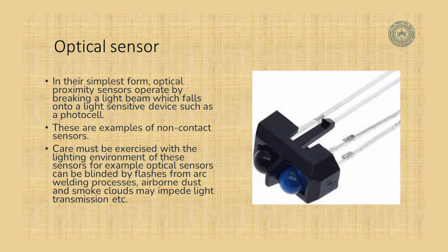Okay. Optical sensors. In the simplest form, optical proximity sensors operate by breaking a light beam which falls onto a light sensitive device such as a photocell. So, they are usually non-contact sensors. Okay. So, you must exercise care with the lighting environment when you are using optical sensors.